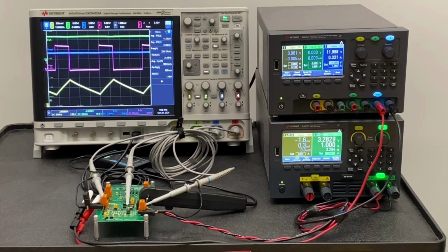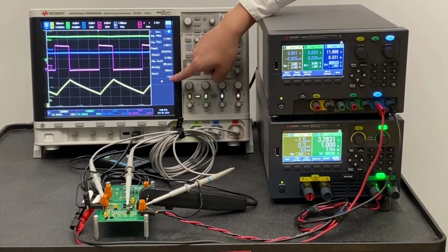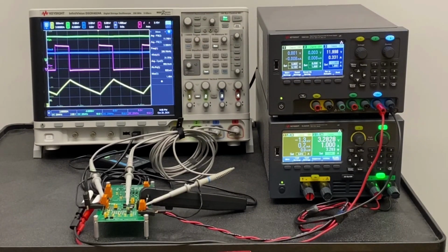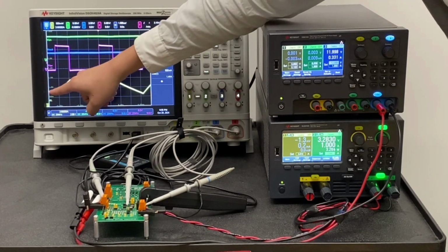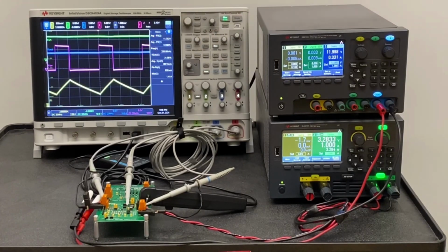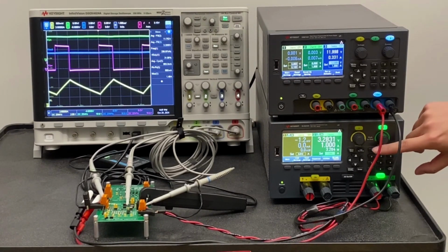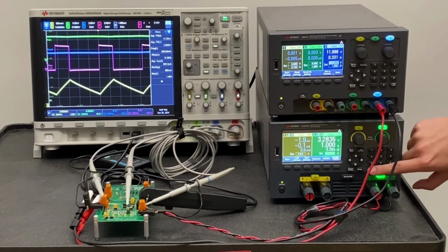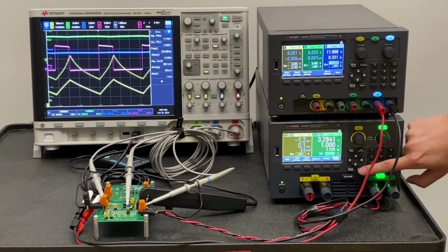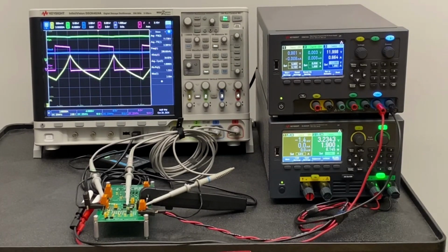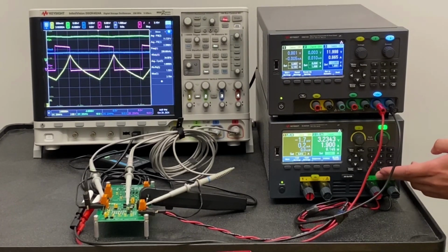Okay. So now, as you can see, when the load current is 1 amp, the peak inductor current is roughly 1.4 amps, which is below the saturation current of this inductor. And therefore, we can see that the inductor current waveform is in the ideal triangular shape. We didn't notice any saturation happening over here. But now, let me increase the load current from 1 amp to 1.9 amps, and let's see what will happen. Okay, so now we have seen that the load current has been increased, and just to be safe, let me stop the waveform on the scope and turn off the E-load.